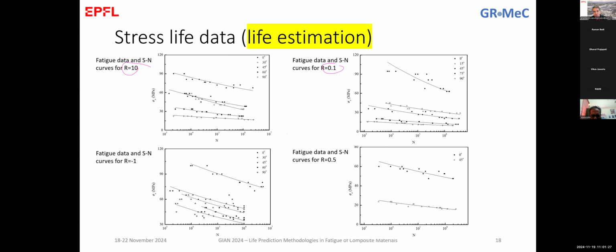So what might happen if we select our ratios that are equal to 0 or infinite is that when we ask the machine to do tension testing, the machine also applies some compressive loads that might be very critical to the specimen, because as we said before, we have slender specimens that cannot sustain compressive loads.